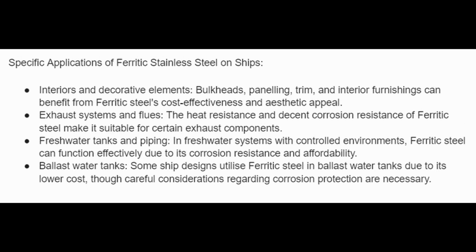Specific applications of ferritic stainless steel on ships: interiors and decorative elements, bulkheads, paneling, trim, and interior furnishing can benefit from ferritic steel's cost-effectiveness and aesthetic appeal. Looks shiny. Exhaust systems and flues. The heat resistance and decent corrosion resistance of ferritic steel makes it suitable for certain exhaust components.